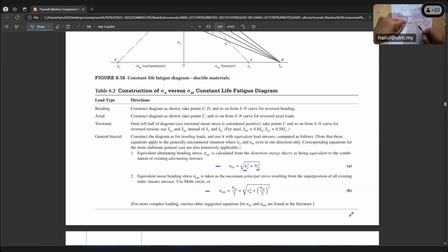All the stresses here are multiplied by the fatigue factor: KF bending for bending, KF torsion for torsion. Understand? We already multiply. This one is also sigma axial. In this case, what replaces sigma bending is only on sigma EA. Right, class? Bending only on sigma EA.